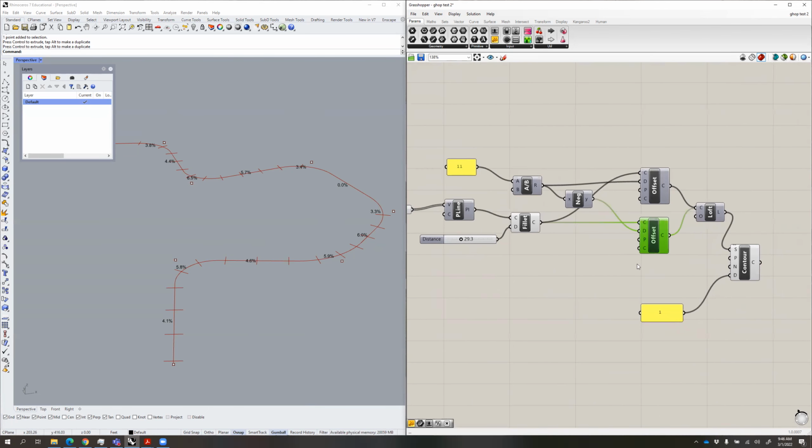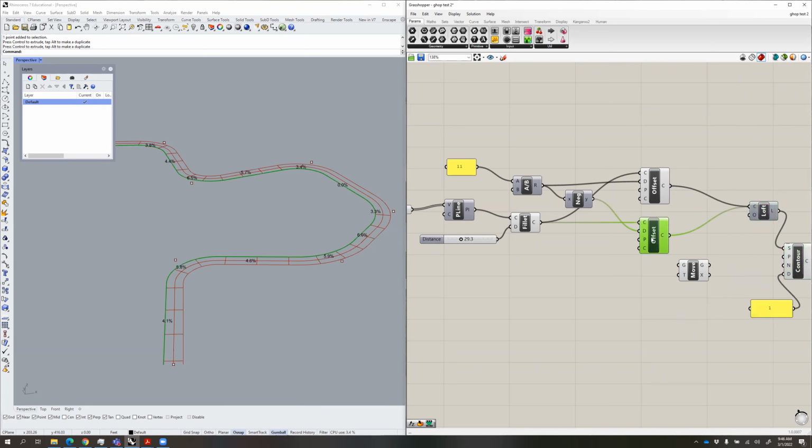at this rate. So what we're going to do is take one of these sides here. We just need to move it down, right? Move it in a vertical direction to build in that cross slope. So we're going to take one of these curves here. Let's take this one, for instance, type in move, right? Move an object along a vector. Let's move this out of the way first. We're going to move this one along a vector, a Z vector.